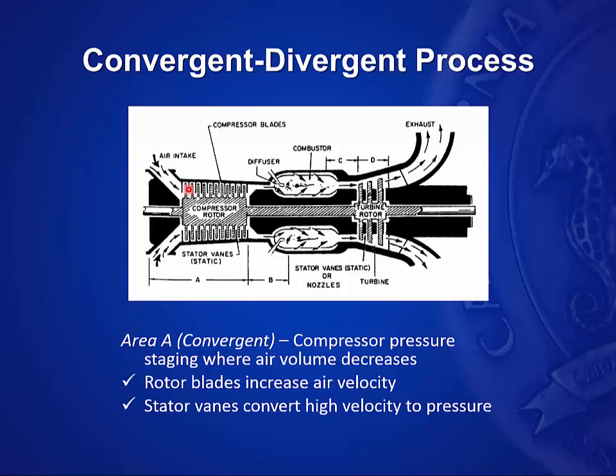air coming out of the stator vane against the next stage rotor blade at the proper angles. In other words, to control the angle of attack. And usually over each stage you have a 1.2 pressure increase. Now that